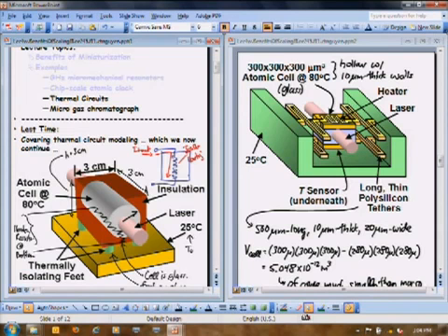So same thermal problem. I have a temperature T0 on the outside of this thing. This thing is being held up by these long, slender supports now, which you can do on the microscale. You have a physics package, which is now very small, 300 by 300 by 300 cubic microns, right? That is a MEMS scale thing. You could see the heater there, the meandering thing on top of this. I'm drawing 4 supports for this. I guess I could even have just had 2 supports for this thing. But now your supports, right, now you're looking at very different values for everything.